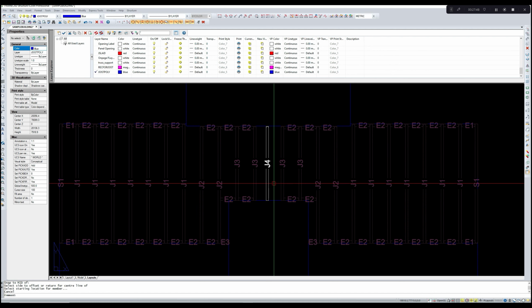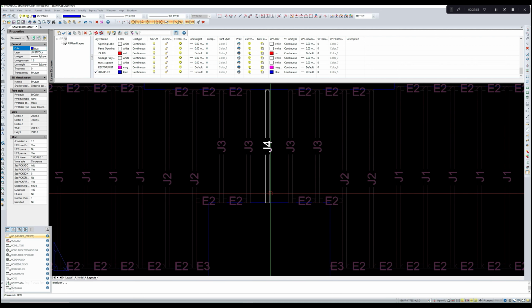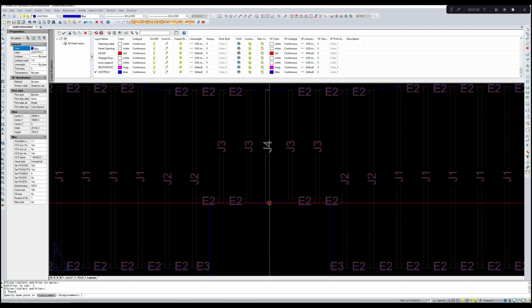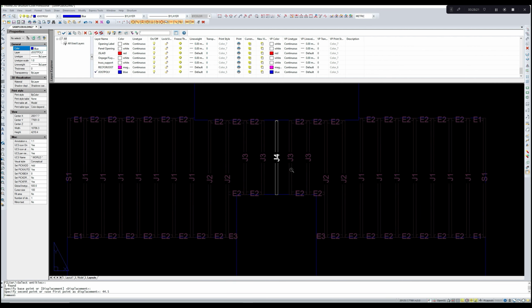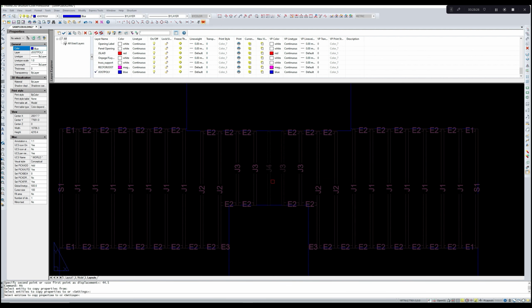The detection with the software is very less. So let us move this joist by 59 divided by 2, 44.5. After picking the base point, type 44.5 on the command bar, then after giving the direction, that should be orthogonal. So the joist is placed at the center. Now let us match the properties of joist J4 with joist J3.